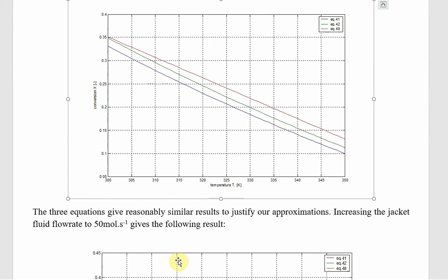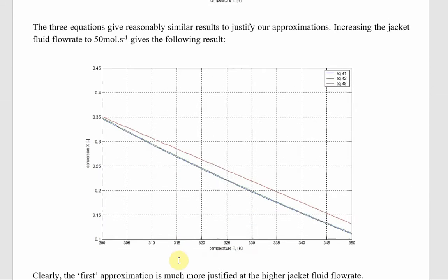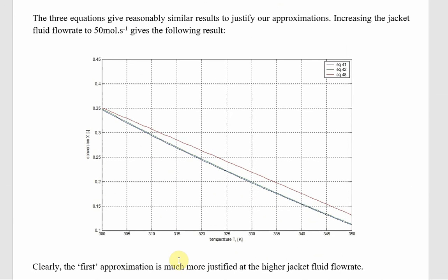And then I also tested that assumption that we made about the heat of reaction being approximately constant. So remember we said delta Cp often worked out to be a number small enough that we could make the approximation that the heat of reaction is approximately the same as the standard heat of reaction. So that's also simulated there. So you can see similar values in each case, and so we can see the conversion is dropping with temperature like so. Okay, any questions or comments on that? Right, I guess there's not much we can say there.